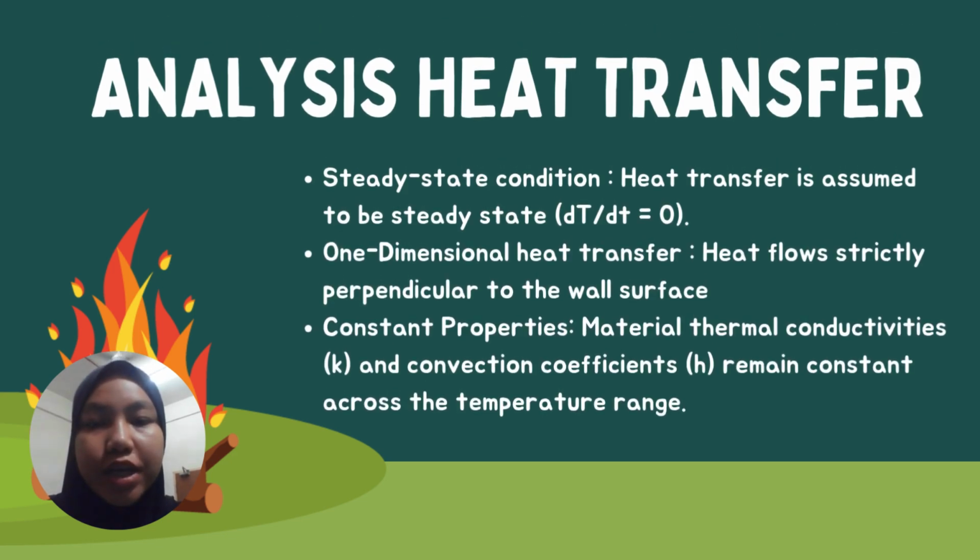So, as for the analysis of heat transfer, first we assume it is in steady state condition, which is heat transfer is assumed to be steady state, and we can say that dT over dt equals 0. Second is our assumption of one-dimensional heat transfer, which is heat flows strictly perpendicular to the wall surface. And thirdly is constant properties. Material thermal conductivities k and convection coefficient h remain constant across the temperature range.